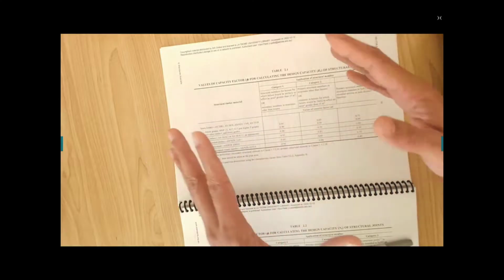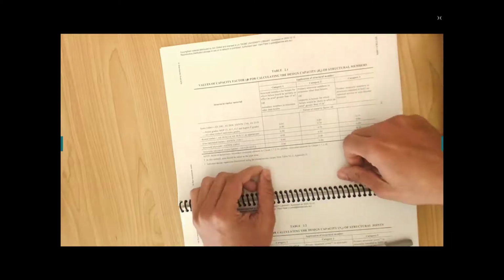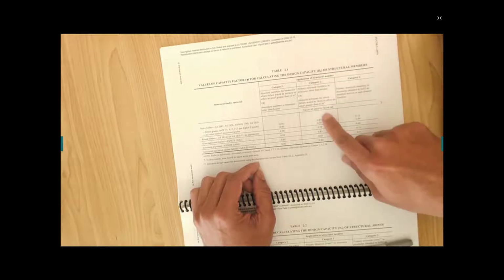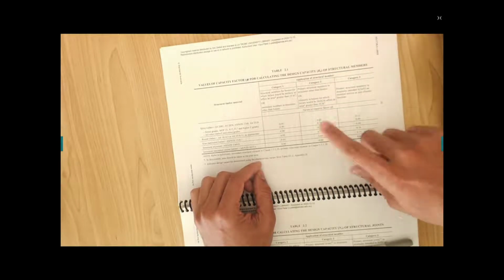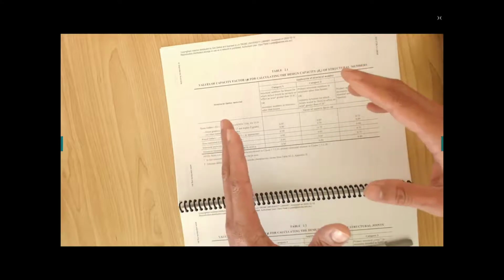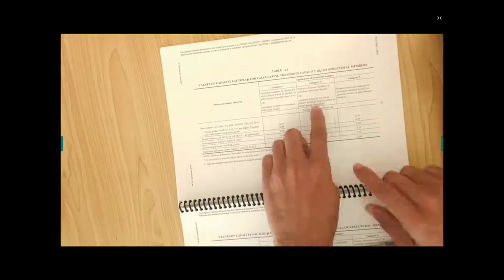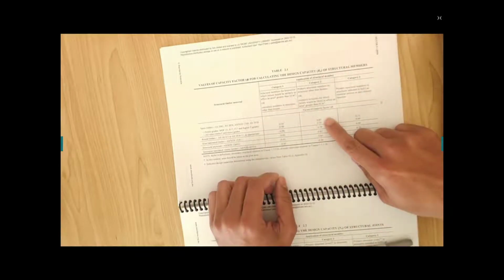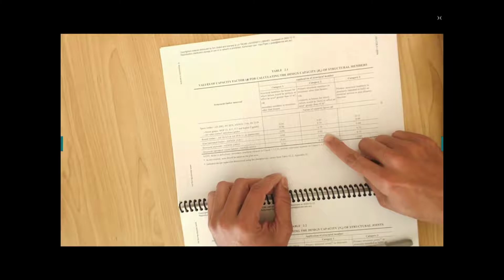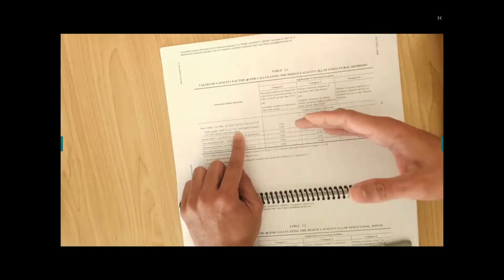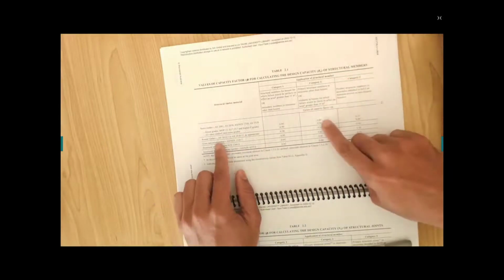So if you have, let's say, 3 bedrooms and all 3 of them are gone and people are sleeping on those bedrooms, then you will have a catastrophic failure, meaning that a higher penalty applies here. So if you are designing the timber members that will break and it will affect more than 25 square meters of area, then your penalty would be up to 30%, about 10 to 30%, about 15, 20 and so on, depending on what grade you are using. If you use a higher grade, like a stronger beam, your penalty would be low.